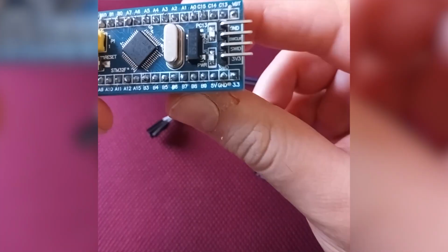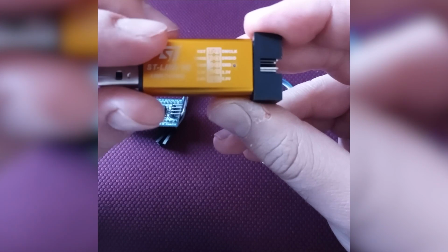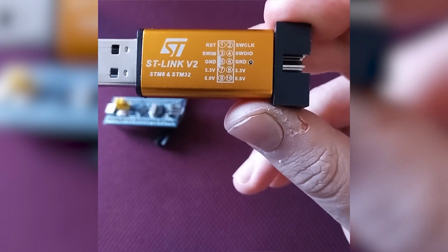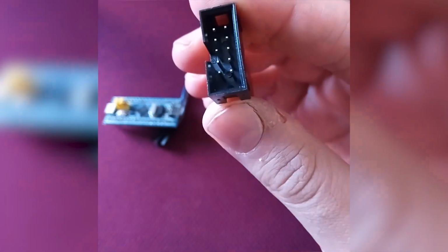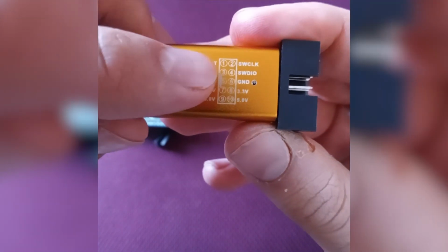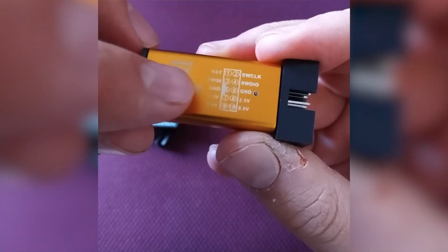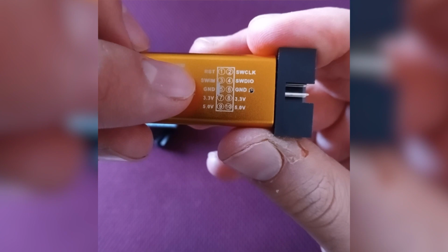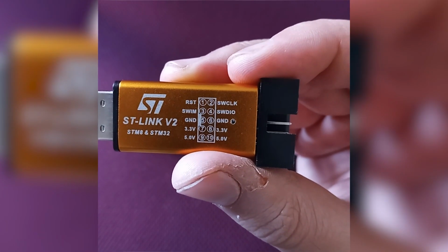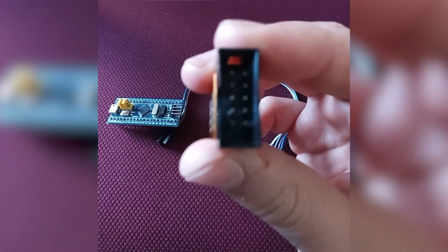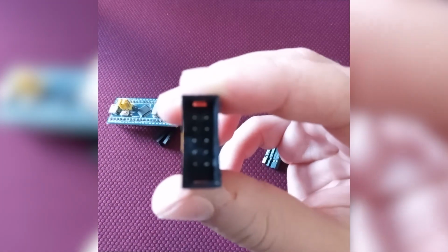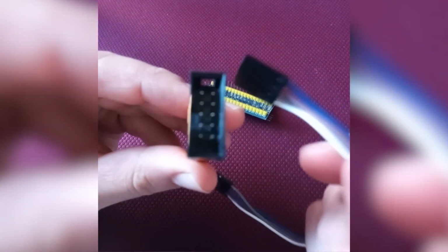The first pin was 3.3 volts. We have to find it here. We have two 3.3 volts pins, pin number 7 and number 8. But how could we find them here? You could see a bold line next to GND. Well, this bold line indicates this port. So when you're looking at this diagram in this view, it is as if you're looking at the pins in this view. So when it says 3.3 volts is pin number 7 or 8, you could connect it to this pin: 1, 2, 3, 4, 5, 6, 7, or 8. It doesn't matter. So let's connect one of these jumpers to this pin.